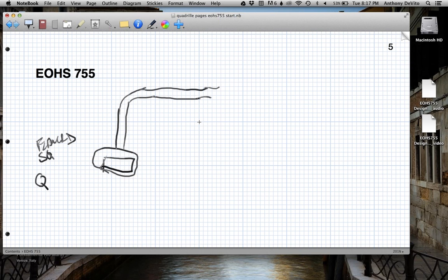Okay, so what does that work out to? Times the capture velocity. Now imagine, what is this guy working with, do you think? You think he's working with some fumes? How about just some fumes? We won't even worry about particles for now. So fumes, typically, 200 is a lot. 200 is what you have at the face of a lab hood. That's a lot of velocity. Let's be a little bit more conservative. Say 100 feet per minute is enough to pull these vapors away from him.